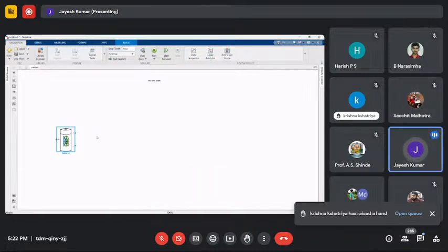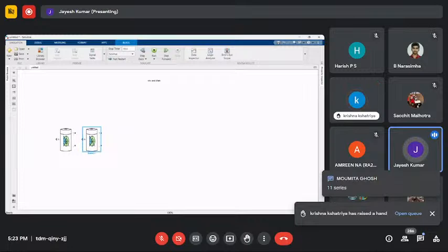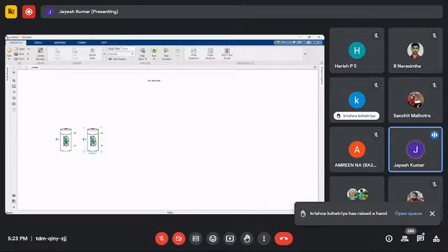Or do we have to connect these batteries in series or parallel connection? Series. Both connections. Both is not the right answer, because I directly set 20 ampere hour in the parameter, so I don't have to connect the batteries in parallel. In series connection, voltages are added, whereas in parallel connection, currents are added. But I have given each battery 20 ampere hour, so you don't need to connect the batteries in parallel.